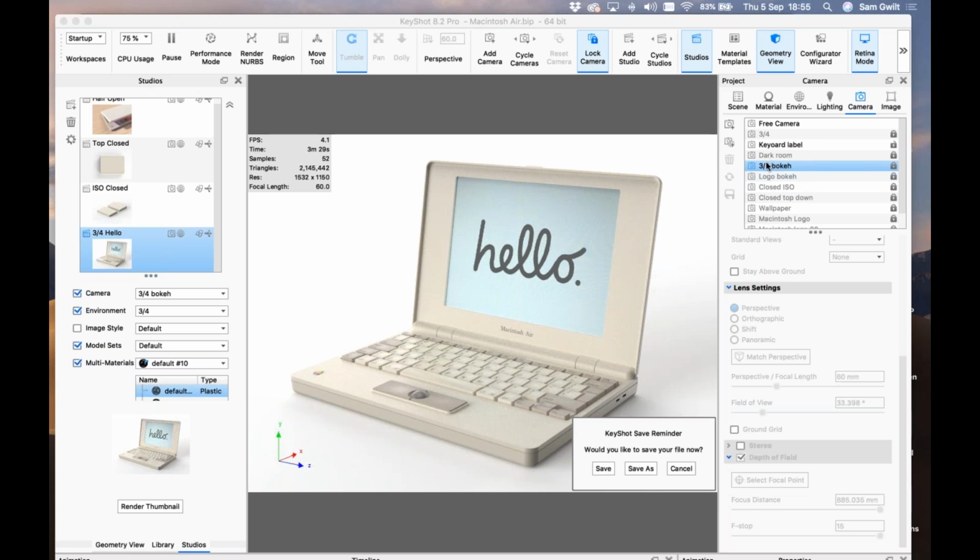Okay, a few questions at the bottom I'm looking at now. The image on the keys was added as a bump. The image on the keys is a decal that I had as one large decal that I've used to map on as one. The materials are all linked together. So if I add it to one material as a planar, it's going to add it to them all. And the same with the specular, which is going to let me have a glossier section in there as well.